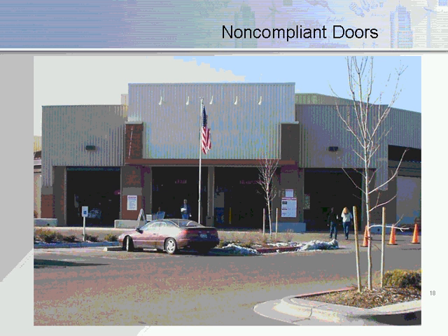Now again, under ASHRAE 90.1/2001, this particular building could be exempted entirely from the vestibule requirement standpoint. And also the two scenarios we looked at with roll-up doors and an air curtain could both be exempted under 90.1/2001 if the buildings were less than 4 stories.